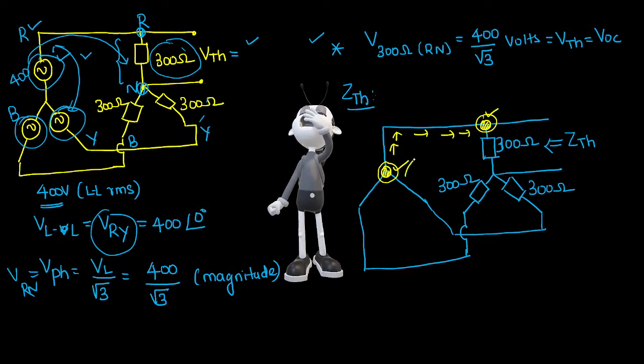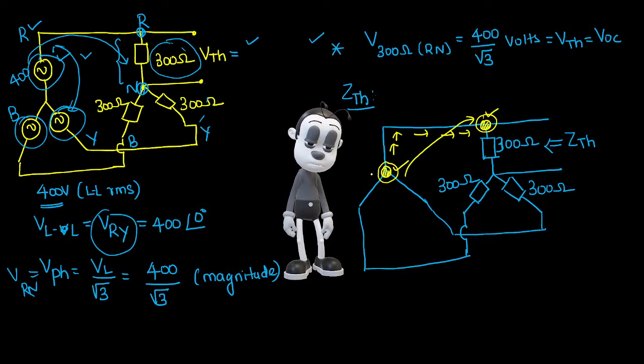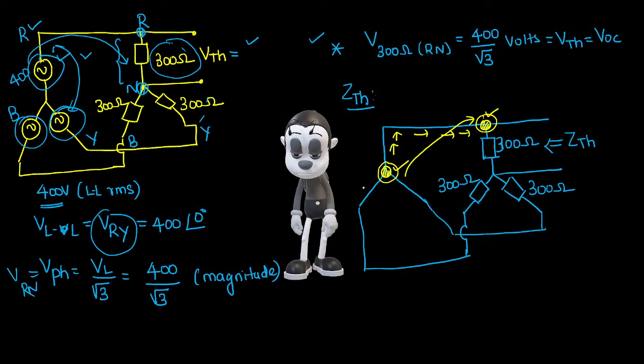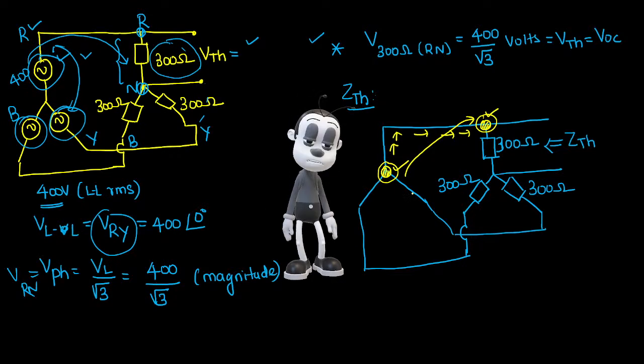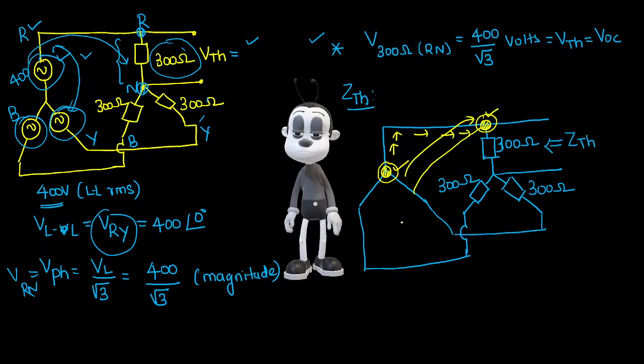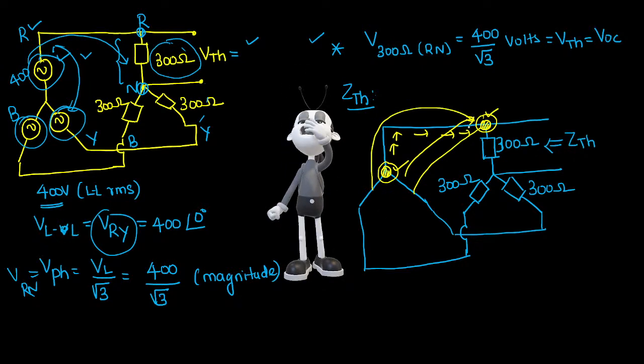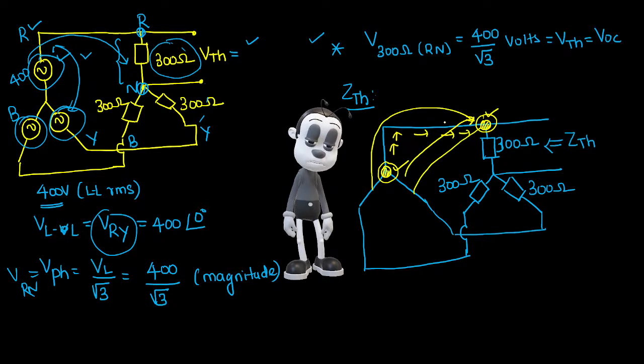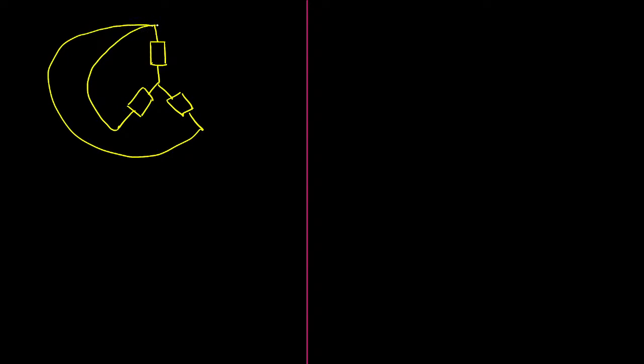So I'm going to simply attach this node with this node. If I attach like that, how will our circuit look? Let us see. If I extend this line directly, connecting it here, and connect this line directly here, I said all are the same. In that case, the resultant circuit will look like this: I have one load here. I have one more load here. I have one more line here. Now I'm going to directly connect this line with this, and we are measuring the Thevenin impedance from here.